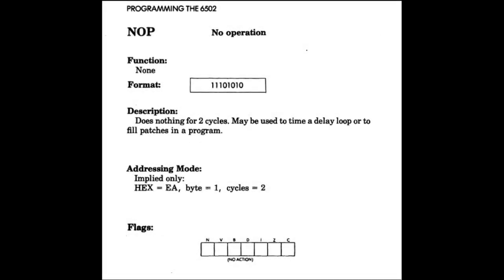So if we want to debug the address bus, let's suppose that we can convince a CPU, in this case the 6502, to always execute this particular operation, which is called NOP, for no operation. What will happen is that it would read this operation and do nothing for 2 cycles, actually 1 cycle, because the first cycle is spent to read this operation from the data bus, and the second cycle is spent doing nothing.